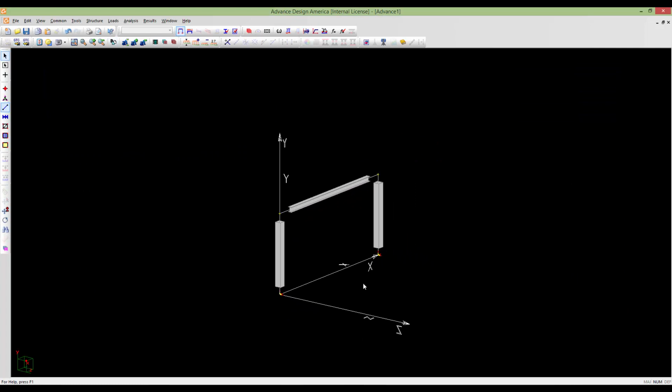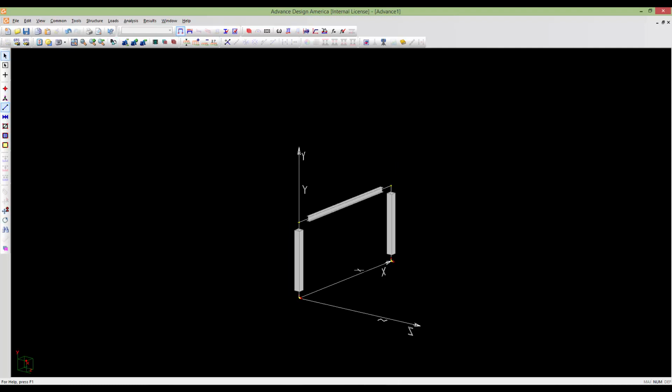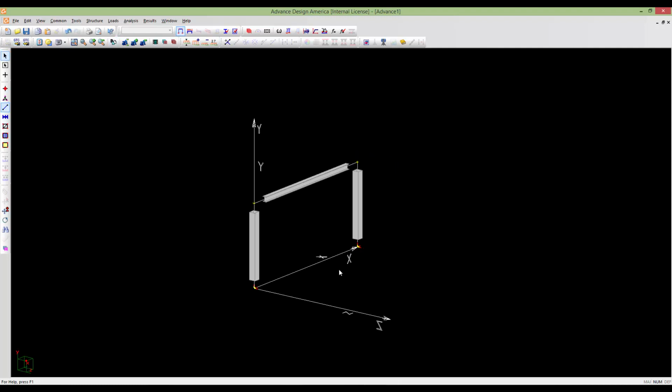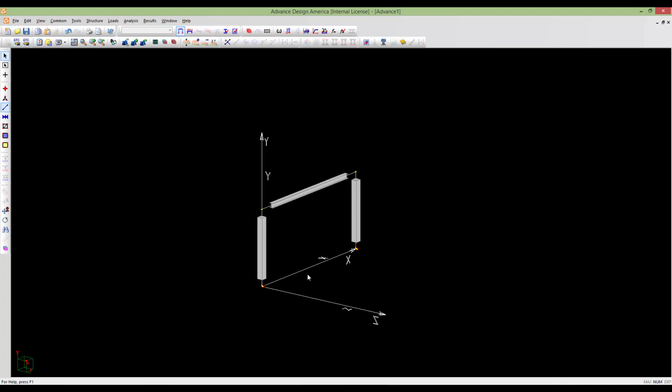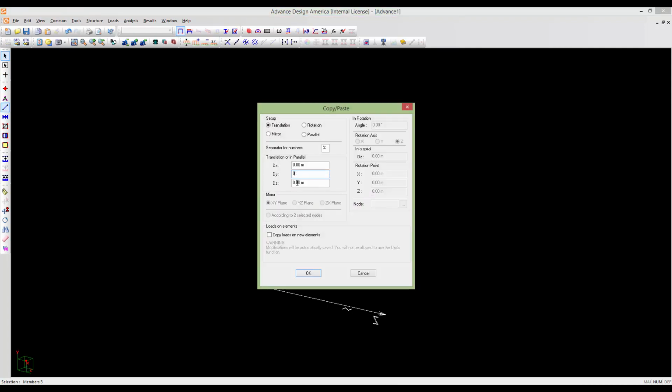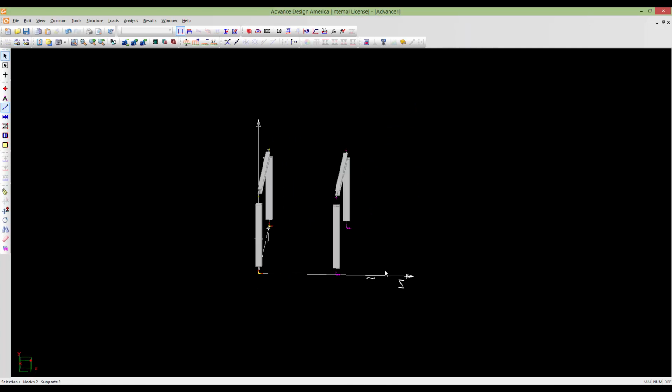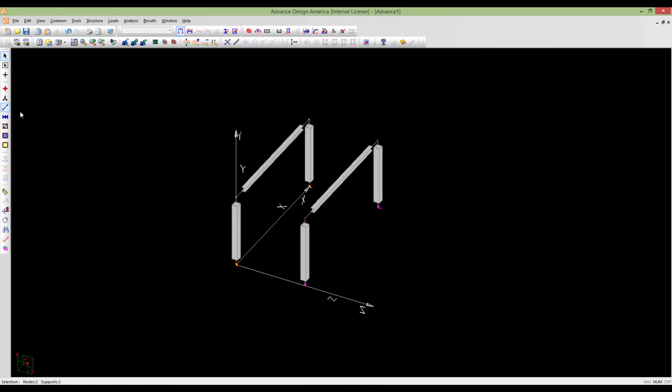Okay. So to show you how to apply also loadings on two-dimensional or roof elements, I'm going to build my model as roof. So select the nodes, Control C, and on Z I'm going to define it as 5 meters, Control V, and add 2 members or beams here to form my frame. And I'm going to add a floor member to my model.